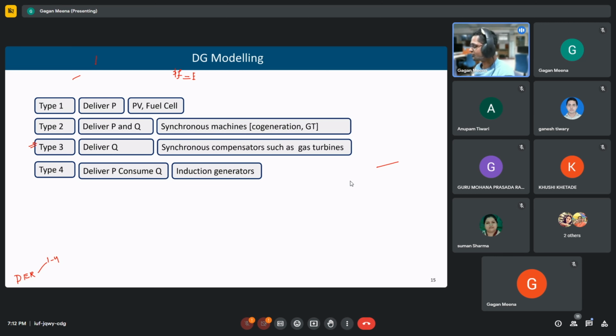So we don't want the power factor to be low. We want it to be close to 1 per unit, a unity power factor. That is why industrial and commercial consumers face a power factor penalty if their power factor is too low. So what do they use to improve their power factor? Generally, shunt capacitors, capacitor banks. And we can also install synchronous machines. Yes, we can use that.